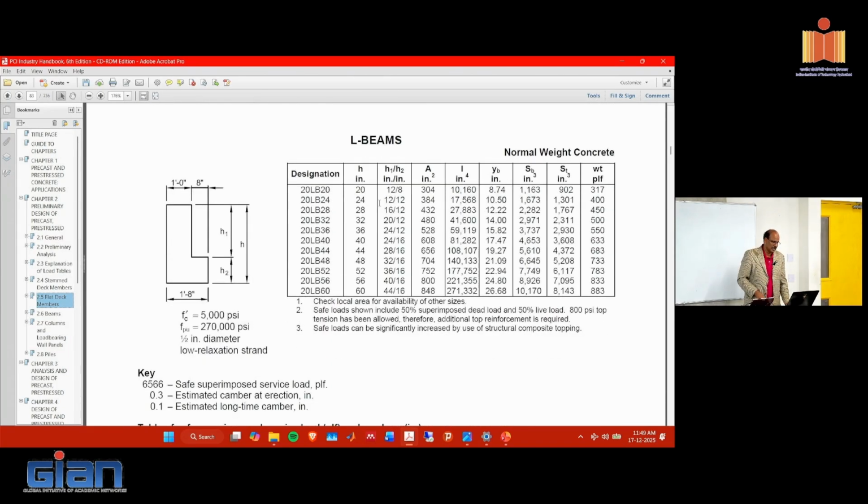I think Satya also touched on this, so there are two types of beams that get heavily used, especially with hollow core and double T's. One is an L beam. So they have standardized the L beam because I think we talked about cracking and torsional effects. So all of that has been done and figured out, what would be the dimension, how it should be detailed, how much reinforcement to put in. So it's not just a dimension, it actually provides what reinforcement to use inside also. You don't take that and use it for yourself directly. That's what is called preliminary design.